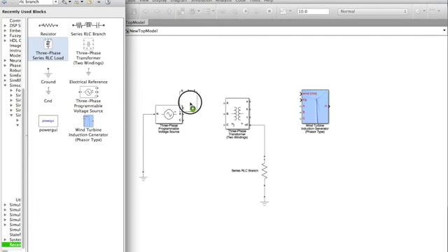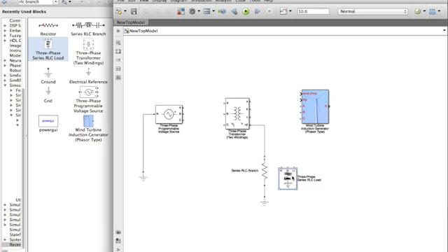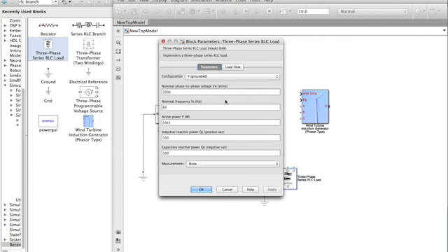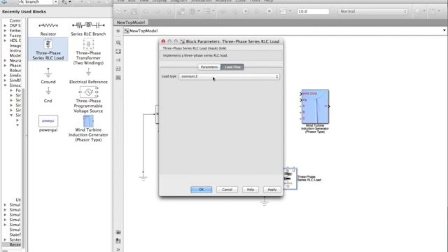Finally, we add the capacitor. The capacitor can be used to create reactive power when connected to a voltage source. We're setting it to delta connection, and using a nominal phase-to-phase voltage of 575, as set up in the transformer. It shall not produce any active power, as this is of course left to the wind turbine. No inductive power, and create 4 megavolt amperes reactive, or 400,000 volt amperes reactive.